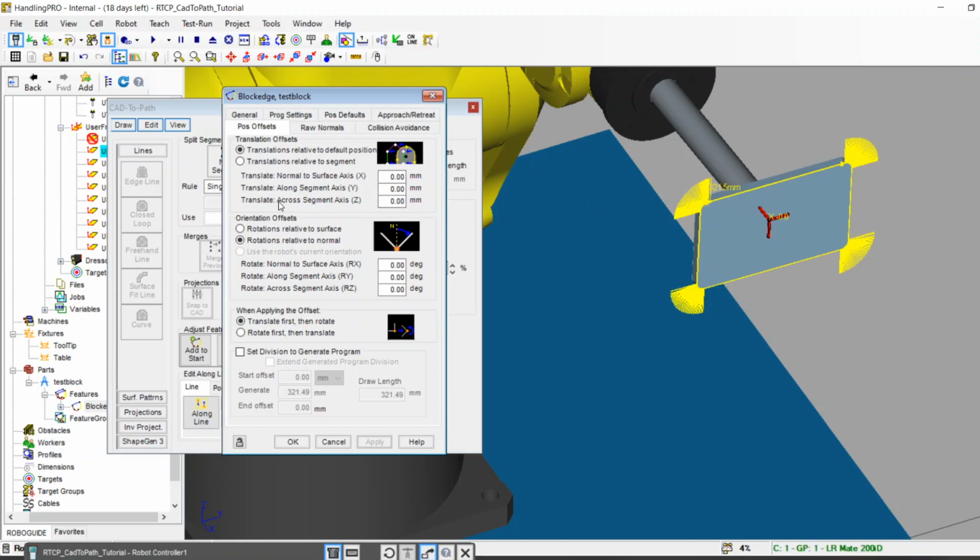I can just bump across the Z, get the part a little farther, more engagement into the tooltip, or a little less, X, Y, Z. You can tilt the part, so you don't have to be at a perfect 0-degree normal. The part could be on a 20 or 40 degree angle or something like that. All things considered when you're deburring.